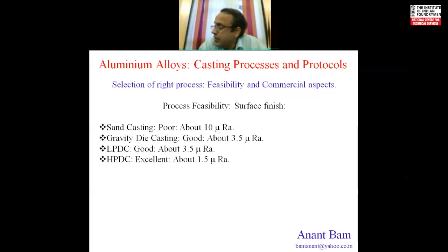There are advanced coatings like nanotechnology coatings, wherein the particle size is ground to nanometer. Such coatings are expensive, but they are able to deliver further better surface finish. All these coatings wear off because every time metal is being rubbed on it during fill, and the solidified castings, during ejection, again rub on the coating. So the coating part has to be repeated every now and then.